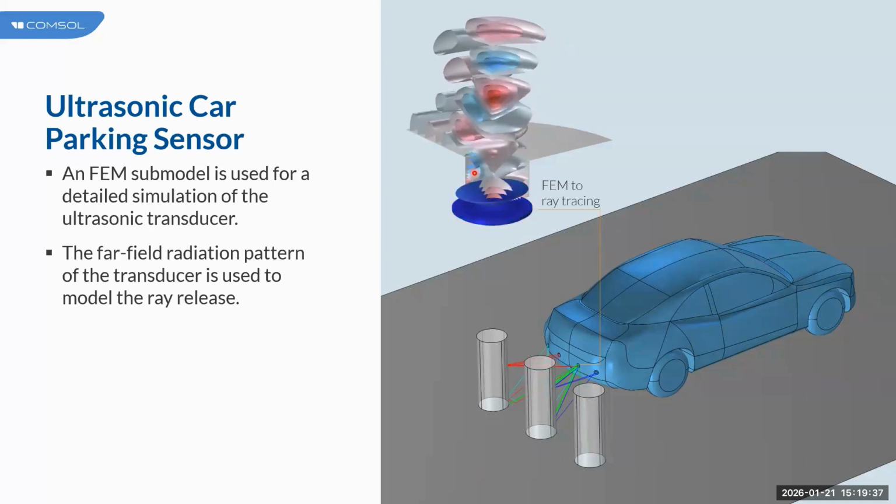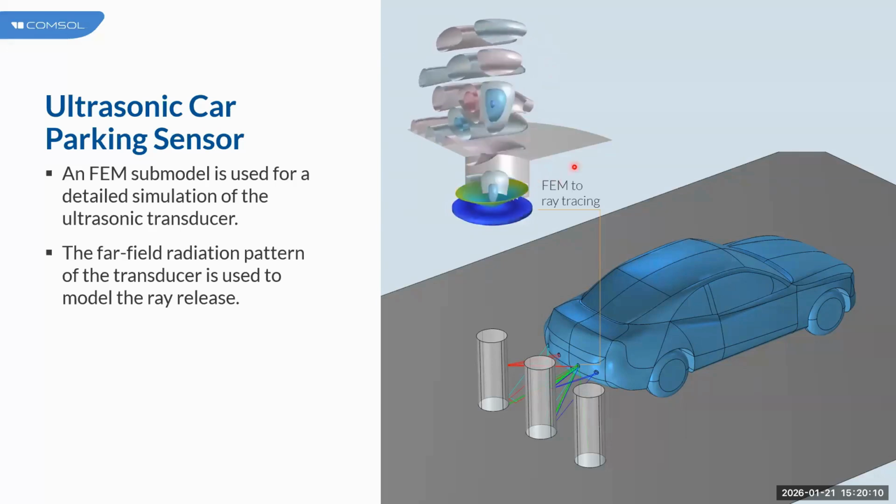So you analyze or design the transducer in detail using the finite element method, and you place the transducer on a very large geometry and analyze the propagation of sound over very large distances using the ray tracing approach. For modeling the transducer in detail, what is used in this particular model is the piezoelectricity multiphysics coupling to model the transducer mechanism, and the acoustic structure interaction multiphysics coupling to model the vibrations from the piezoelectric material that generate the sound in the fluid domain and propagate outward.